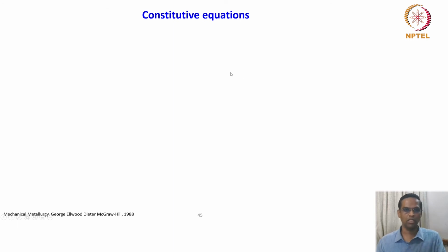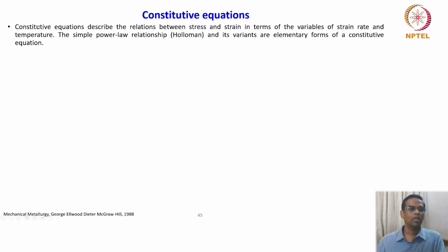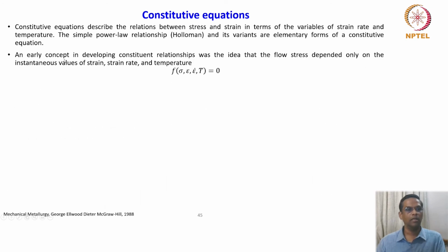So we will look at some of the constitutive equations which are very useful and important for further discussion in this subject. So what are constitutive equations? Constitutive equations describe the relations between stress and strain in terms of variables of strain rate and temperature. The simple power law relationships like Hollomon and its variants are elementary forms of constitutive equations. And an early concept in developing constitutive relationships was the idea that the flow stress depends only on the instantaneous values of strain, strain rate, and temperature.